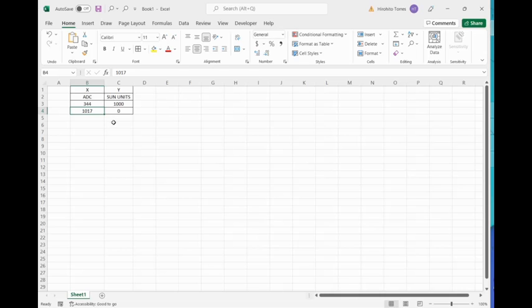So we want to do a calibration now. What does that really mean? Well, what it means is just do whatever you do. Like for example, let's do here. So we have the points here. Let me be sure that this makes sense. On the X and Y, in the X I have the ADC, and the reason why I have the ADC in the X is because this is the value that's going to be read by the Arduino, and that needs to be converted to some units. Basically, my graph here will be this on the X and this on the Y.